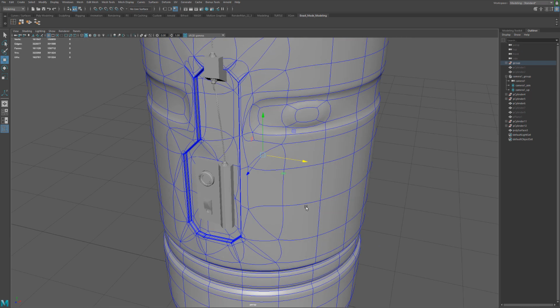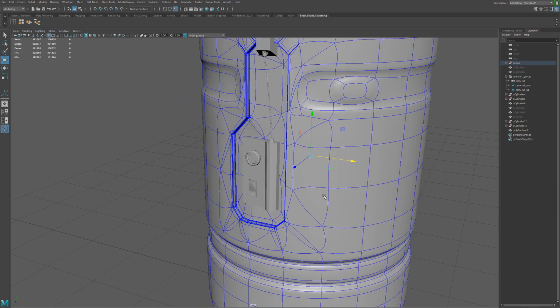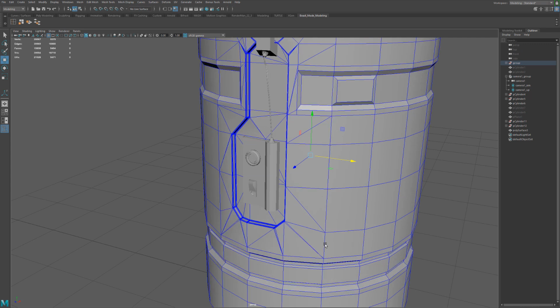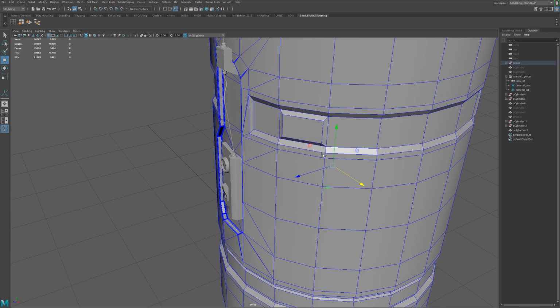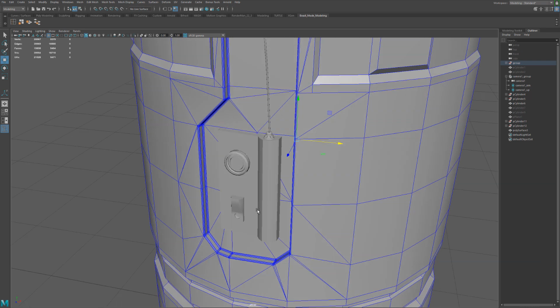The challenging thing about this shape is that this is probably one of the most ruthless and hardest shapes to actually model, especially if you're a beginner, because you have to think about it like this. You have this cylindrical shape that's symmetrical, perfectly radial, right? And then any edges that you add, especially if they're not conformed and perfectly pushed out, are going to break the continuity of this perfect cylindrical shape, right? So one of the things that could definitely help is starting with a denser cylinder, right? And that's what I'm going to do.